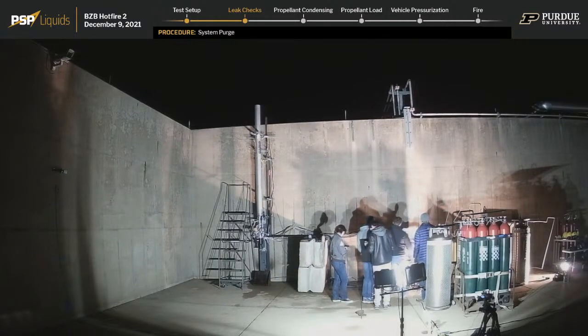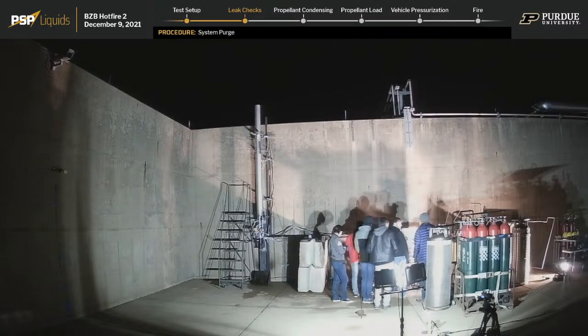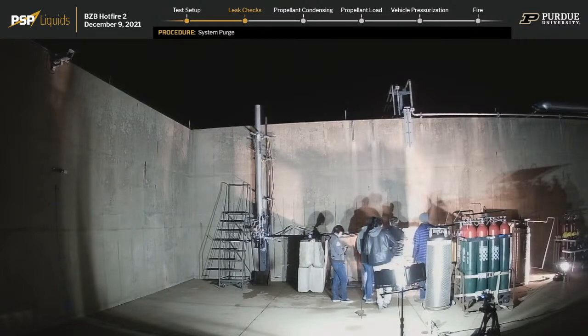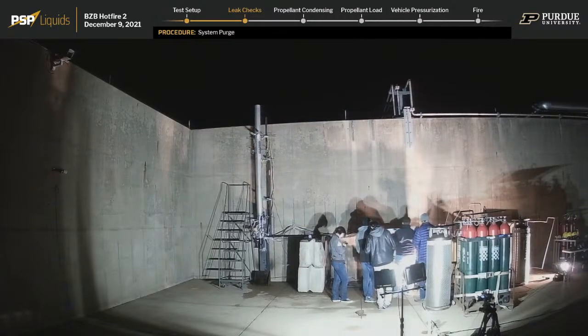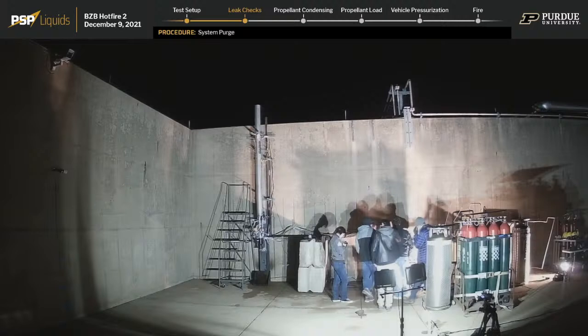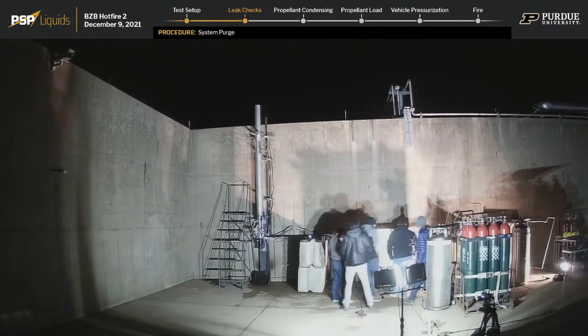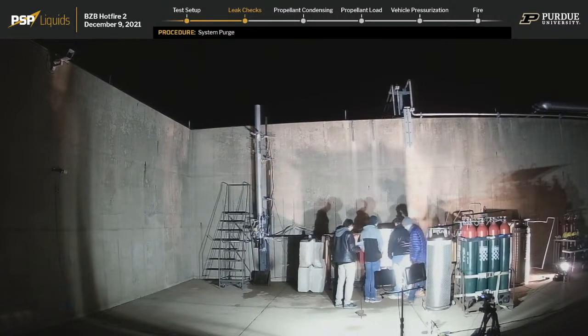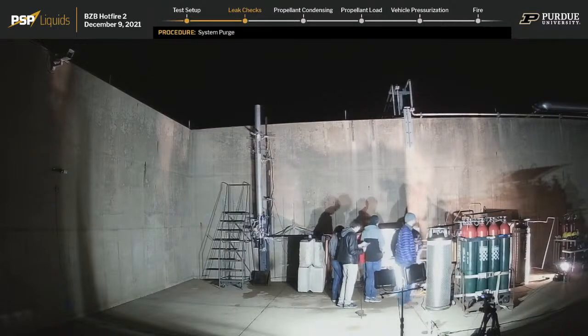MRHE02. So of course right now MRHE02 is open. Over. We are just getting our bulk nitrogen ready to go ahead and purge the system. Close MVN201. MVN201 is closed. Go ahead and open MVN202. MVN202 is open. Open MVN203. MVN203 is open.